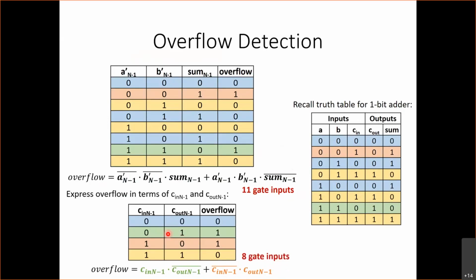There is a reason. There's kind of a logical reason why this happens. If my carry in is 0, but then my carry out is 1, it means I have 2 1s in my most significant bits. But if I carry those out, that means the remaining value is going to be a 0. So here I had 2 1s become a 0, and that's kind of what's going on over here. Okay, any questions about overflow?